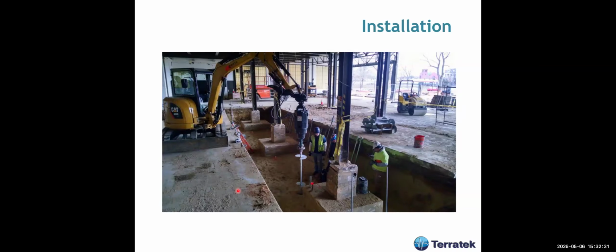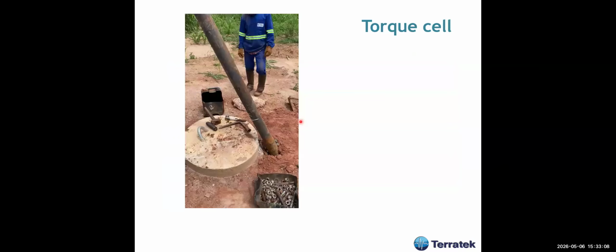They can be installed in very confined space. I have done this in, for instance, an existing airport. I might have a photograph of that, in which the design was with micropiles, and I replaced it with screw piles. The advantage was very quick and very small space. The equipment necessary is very small, just a hydraulic excavator like that. We replace the bucket by a hydraulic motor, and then you can install the pile.